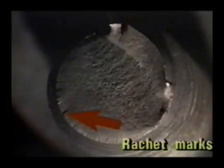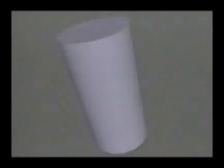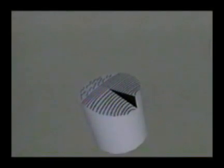Ratchet marks may or may not be present on a fatigue fracture. They indicate high stress and multiple initiation sites. That is, several fatigue cracks may have started at nearly the same time and near the same location, but on different planes. As the fatigue crack grows, the individual fractures may join together and form one large crack. The ledge between the cracks is called a ratchet mark.